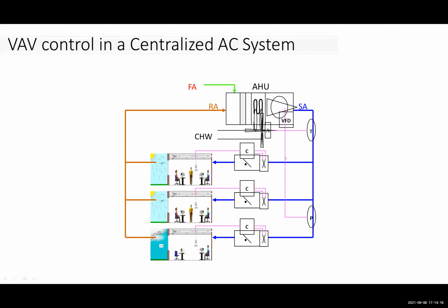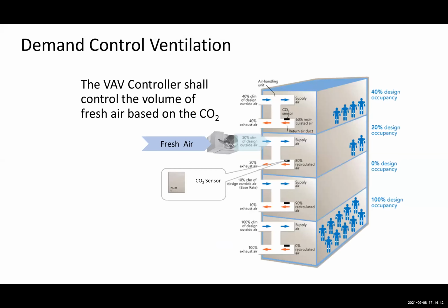So these are some of the ground realities that we need to know when we design, operate, commission and put the system into operation. Revisit it, get the set points back again, and ensure that whatever performance was estimated at the design stage, the same is what we get right through the life cycle of the equipment.